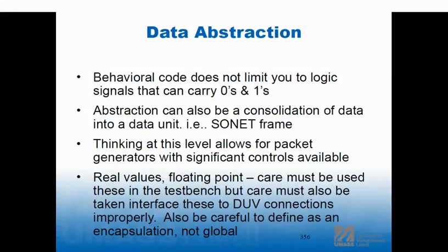So now my abstraction is something that randomly creates instructions because instructions have five fields in them or something, right? Destination register, source register, operand, all that kind of stuff, opcode. So I'm generating instructions with separate constrained random variables that dump things in, and then I'm checking to see if it works. Just to continue with this thought experiment a little away from what we're talking about here, I would do that for a really long time.